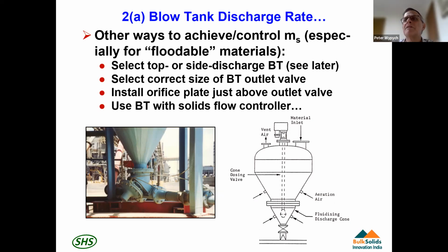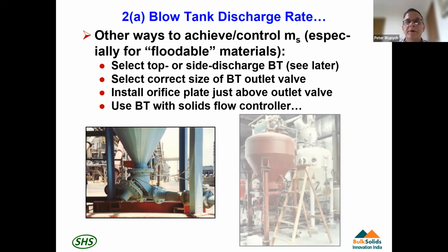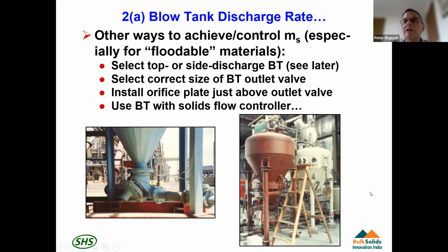For many standard pneumatic conveying systems, this is a bit of an over-complication. But actually you can see here the first blow tank in our lab is the one on the right, which I'll come back to later. And that has got a pneumatic logic controller, which, as mentioned earlier, is for underground mines. So there are no electrical components here. It's all done pneumatically.